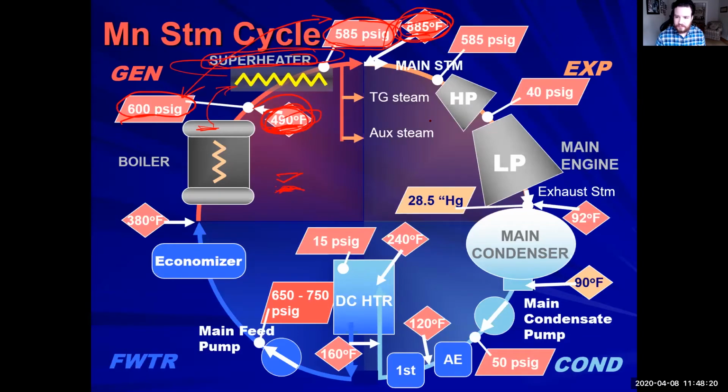So, you cannot have water molecules present because of the force and the speed that this steam is going into these high-pressure turbines, which will be highly damaging to the blades. They will impact those blades at such a high rate of force that you can have severe damage done to the turbine blades.